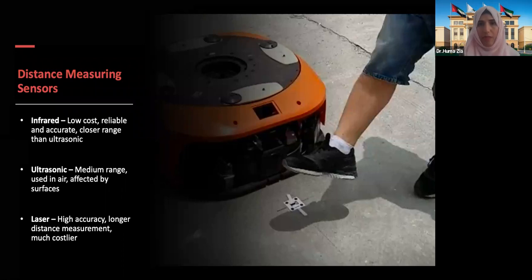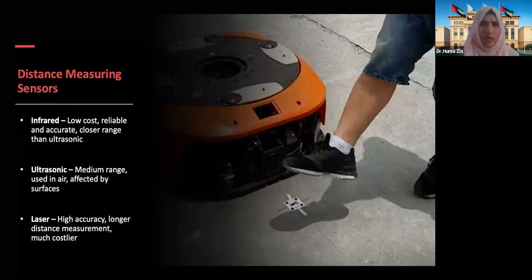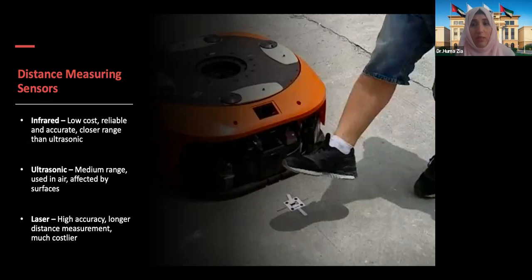Okay. Now, just a little briefly about the different kinds of sensors that are there. Distance measuring sensors include infrared, ultrasonic, and laser. Obviously, they all provide different kinds of ranges, and the costs are different. Infrared is low cost, reliable, and accurate, with a closer range than ultrasonic. Ultrasonic is medium range, and it is affected by surfaces. Laser has higher accuracy and can measure distance at a longer range as well, but it's much costlier.